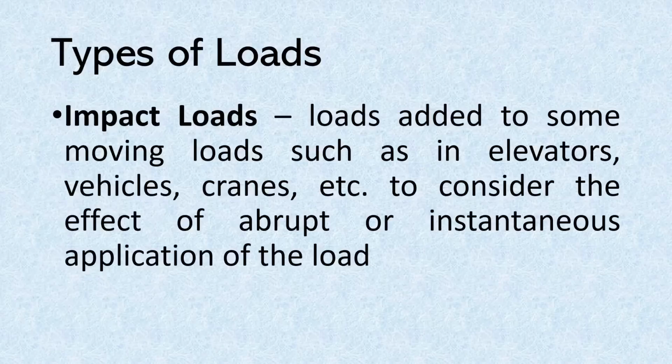And then we also have impact loads found in elevators, vehicles, cranes, and the like, which entails the instantaneous application of load. And then this may also be seen in beams subjected to impact loadings. Let's say something fell from this height, and then this is our beam. If this strikes the beam at this point, then that will be considered an impact load. And then usually we just consider the static deflection and then multiply it by the impact factor. But this no longer comes out in the board exam. Maybe only in undergraduate studies.